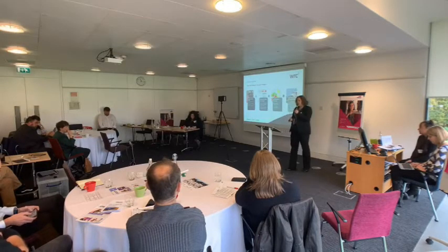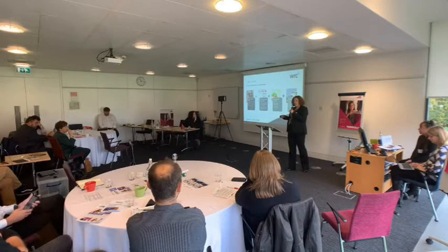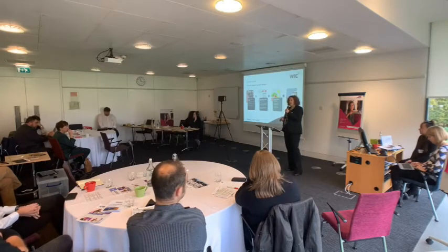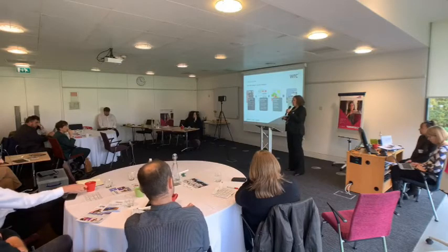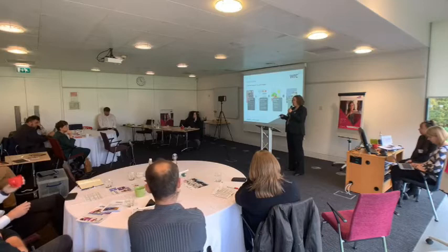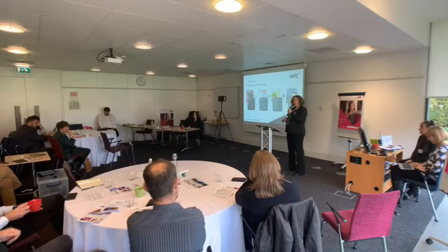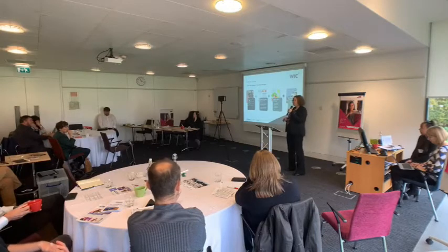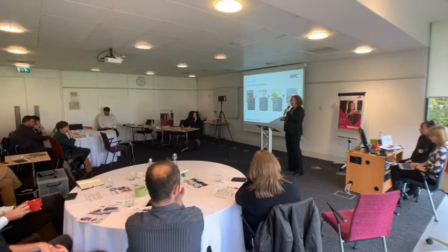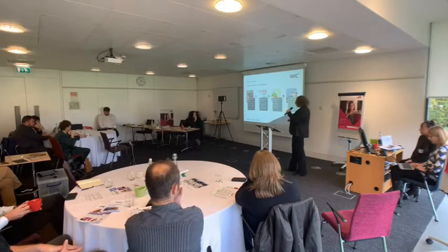So asset records of large meters, DI meters everyone knows about. They have to be verified, so that people know where they are and what they are. They might not be very good, but they know what they are. DMA meters sometimes have been fit and forgotten. Interstitial meters, that's a fancy word for ones in the middle of a network that aren't necessarily serving a real purpose, often we don't have a clue. You might know there's a meter in the ground, but no one really knows what it was or where it came from. So making sure the asset records are there is quite important as well.